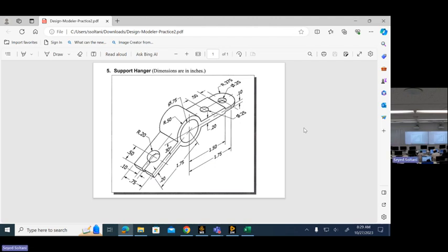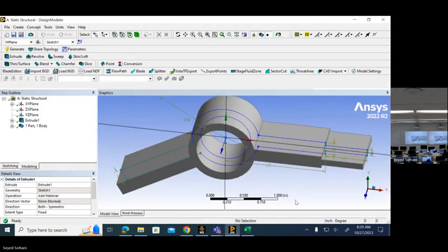All right. So if I go back to my drawing, I see that the circles, if I want to build them correctly, belong to a different plane. They do not belong to the XY plane where I built my first sketch. They actually belong to the XZ plane. Right? So I had to create a new sketch in the XZ plane. How do I do that? I first need to select that plane.